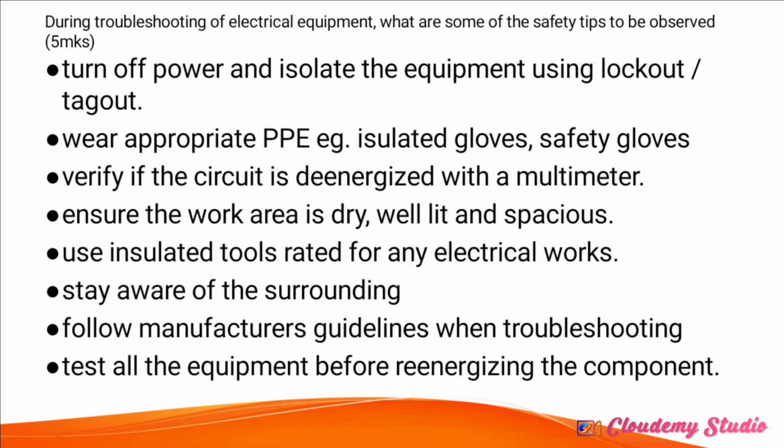So after you've finished, and if you go back to our notes in class, we talked about the procedure. That procedure, I said, is where before you insert the power source, after troubleshooting the equipment, you have to test by the use of your testing instruments, your multimeter. That test that we always tell you during practicals: perform a continuity test, perform a polarity test, perform an insulation resistance test. Those three tests, we are trying to ascertain that before you put in that power source, you make sure that those three tests are in line.